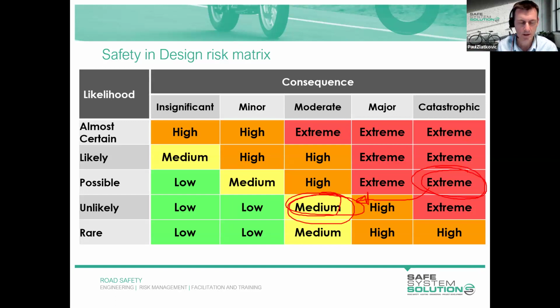This was one control measure that I'd identified, and there's no doubt there are going to be others available. I think yesterday was one of the quizzes. Road closure is certainly an option, to allow people to work without any exposure to live traffic. I think that's the key. The premise of the so far as is reasonably practicable approach is that we continue to minimise or eliminate that risk where we can, if it's reasonable to do so.